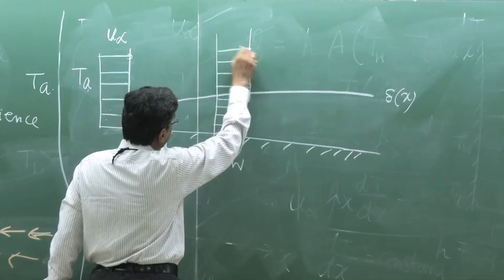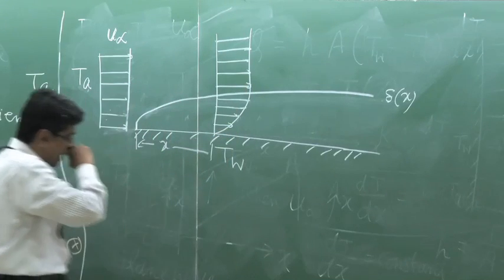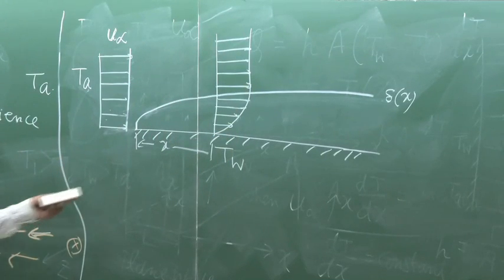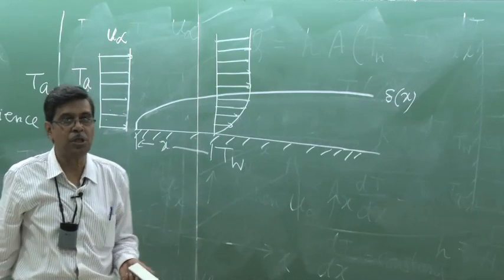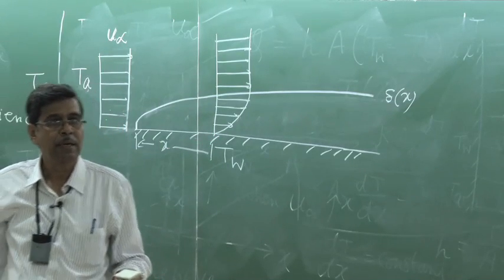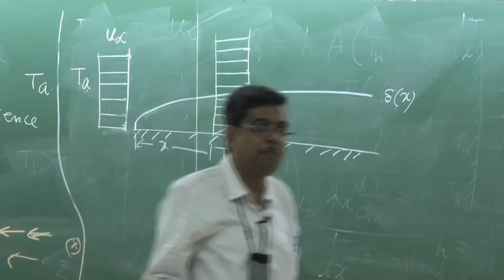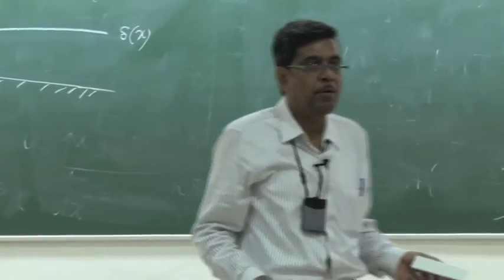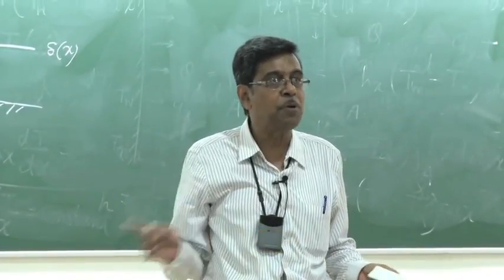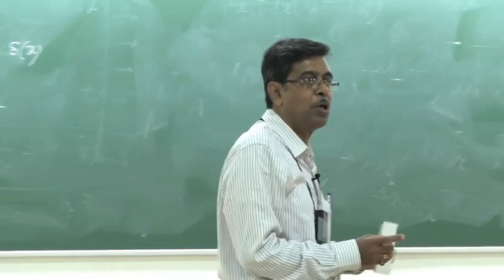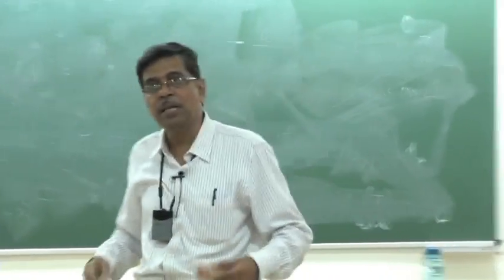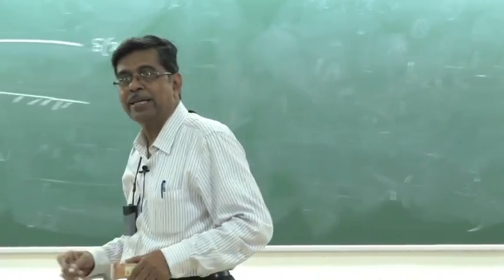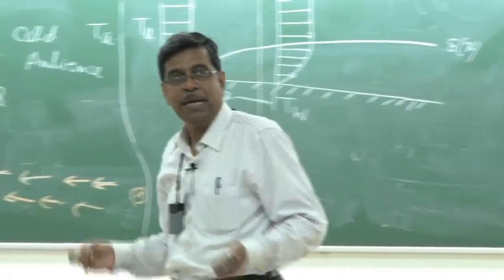Recapitulating the fluid mechanics concept, what happens? The fluid velocity at the solid surface is zero relative to the surface, which is known as the no slip condition. In the domain of continuum, the fluid particle cannot slip over a surface because of strong molecular adhesion. Under very special cases, even in the domain of continuum, an effective slip appears at the surface.